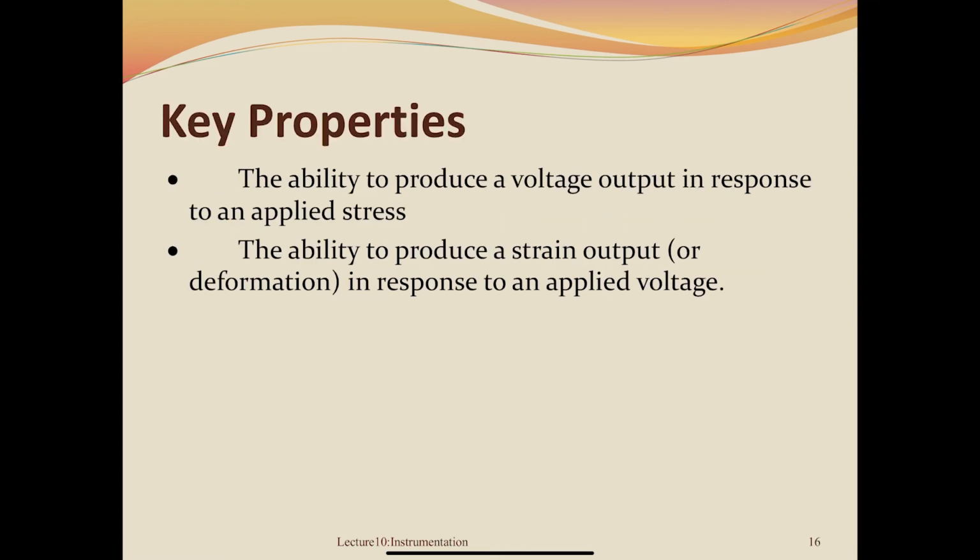The important key properties in piezoelectric is the ability of the crystal to produce voltage when we apply a stress, and also the ability to produce a strain output when responding to the applied voltage. So this one is the direct effect, and this one is the converse effect.